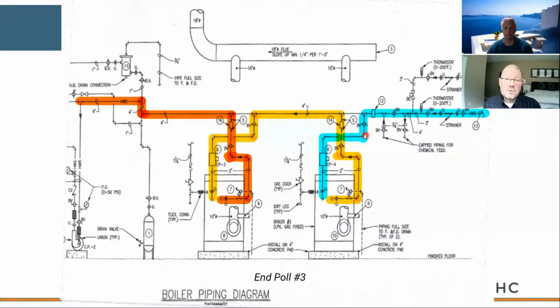Okay. To fix this, you would take cold system water, bring it in here to CP4, but you'd also continue it over here into CP3. So this blue line would continue over. The hot line that leaves boiler 3 would simply tie over in here to boiler number 4.